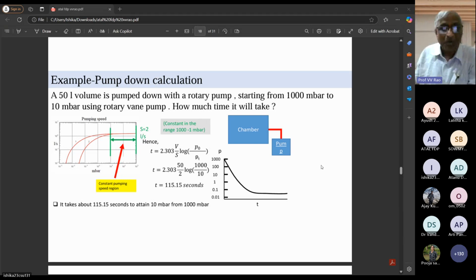High vacuum pumps are pumping parasitic gas loads and process loads. Whereas the normal vacuum pump removes 99.9% of the gas, and it's not costly at all. But these parasitic loads, to be removed from 1 torr to 10 power minus 10 torr, are only micrograms and nanograms, but all the applications are there. Up to 99 runs, nobody cares. The last one run is very important. Same thing in vacuum technology. 99.9% of the gas has been removed by that 20,000 rupee rotary pump. And within 10 minutes, that 0.1% gas, going from 1 millibar to 10 power minus 10 millibar, will take more than 20 hours.